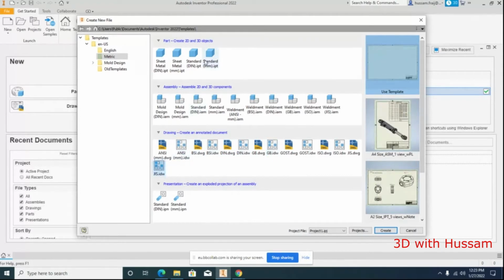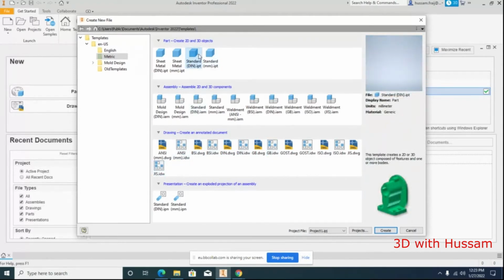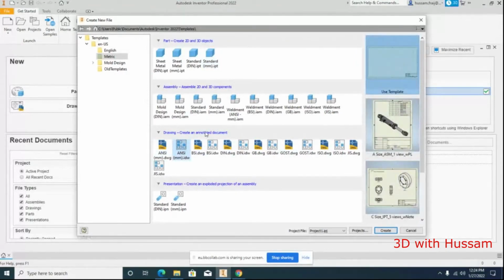Like when you have a 3D model and you give the shape. As an example, can you see here down, you will find here shape, thumbnail. This shape, if I give you this shape, and I will tell you, take this model, picture, I give you a picture, and go manufacture it for me. It's a 3D, I take an image on the phone, and you go manufacture it for me. How will you manufacture this? You will not be able. Why? Because you don't have measurements. You cannot print it on a 3D printer, you cannot put it in the CNC machine, you cannot put it in a router, you cannot do anything because you need dimensions. From where do I put the dimensions? In this one, in drawing.